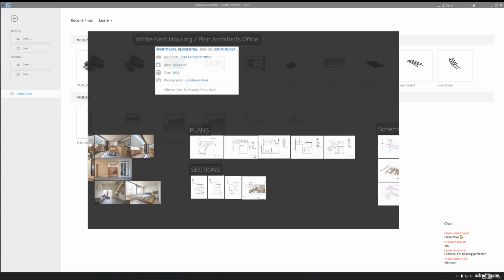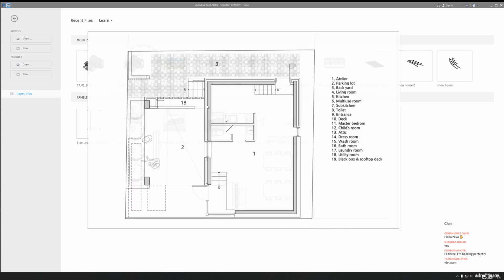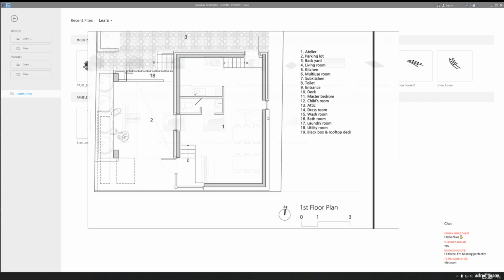Okay, we finished this first floor. I did the external walls, I did the external things with this brick wall. We continue with this concrete wall. We should create our concrete wall, and after that we will continue on the second floor. The first main thing is that we should create the core of our building.